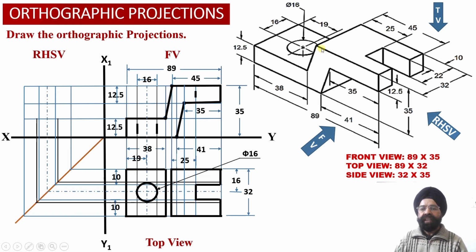Next, we have got this top surface of the element number 3 over here. Corresponding to this element number 3 top surface, here we have got a rectangular slot and here we have got a flat surface over here. Now we can check, since this top surface corresponding to element number 3 happens to be parallel to the horizontal plane, we have been able to obtain the true shape projections corresponding to this top surface of the element number 3.